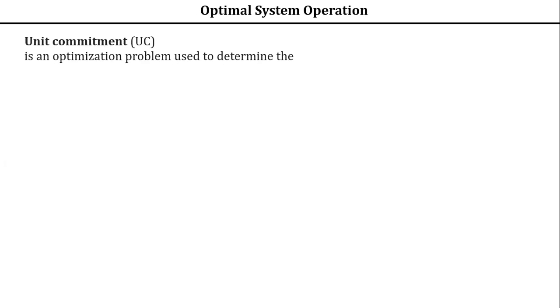For the first hour, morning 8 to 9, these units we have to switch on. Next, 9 to 10, these units are to be switched on and these units switched off. Even if a unit is switched on, what is the load, what is the generation, that has to be decided. Suppose out of 7 units, unit 4 and unit 7 should be switched on between 8 to 9 a.m. Or you can do a combination of three, say units 2, 4, 7, or you can switch on all the 7 units.